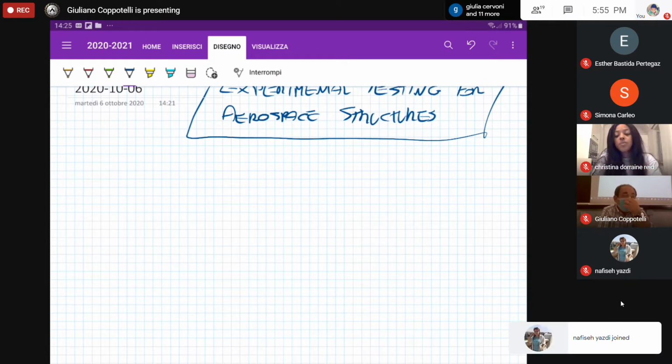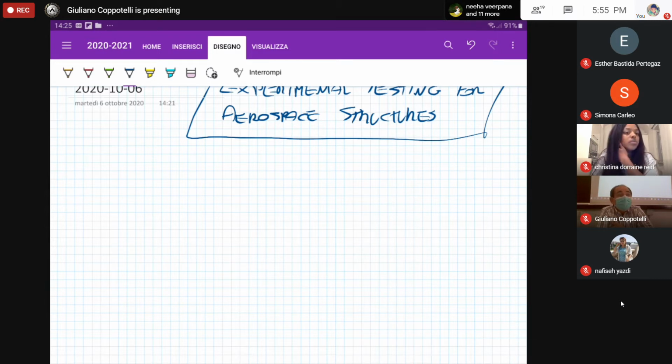It means that we are operating the strain gauges at whatever temperature. So there is no temperature reference but the one that the manufacturer is telling you. Okay, so I could be in a reference operating temperature equal to, let's say, 100 degrees, if my strain gauge manufacturer is telling me so.